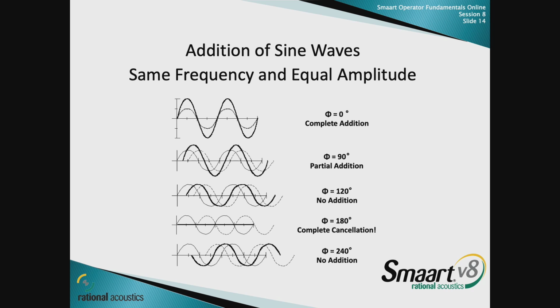Now, one of the things I want to point out here is that the horizontal axis, the x-axis, is time, right? It's marked in quarter periods. But basically, phase shift connotes some amount of time. So phase shift is sort of a time mechanism. But for the one where I've got 180 degrees of phase difference, I can actually get that without shifting in time. I can get that by an electrical system just swapping positive for negative.